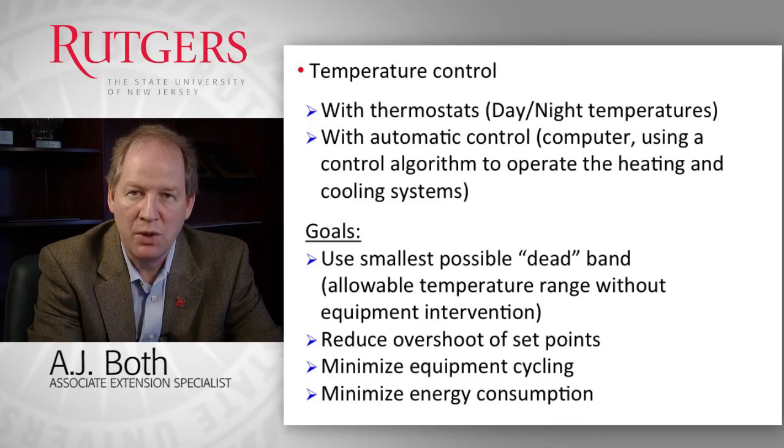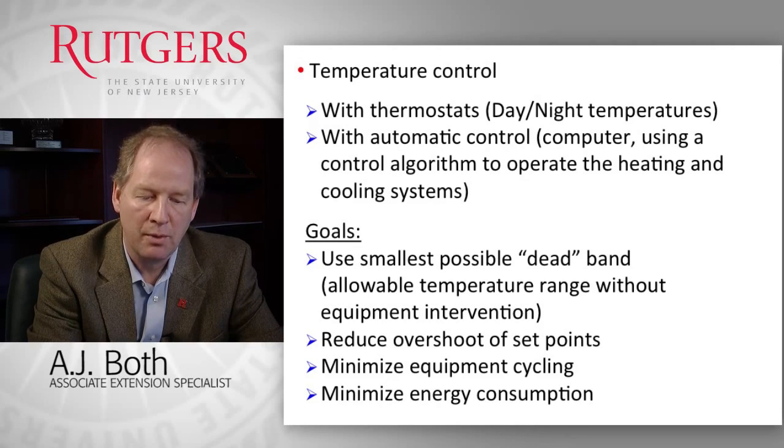allow a deadband in which we do not operate any of the control systems. So let's say the deadband in our case would be from 69 to 71. So only at 71 degrees Fahrenheit would we start cooling the greenhouse, and at 69 degrees we would start heating the greenhouse. And we do this to try to minimize the back and forth between the various control systems that we use to maintain the proper temperature. And so the trick is to have the smallest deadband that is allowable to maintain the temperature without having the systems fight each other all the time to maintain the proper set point.